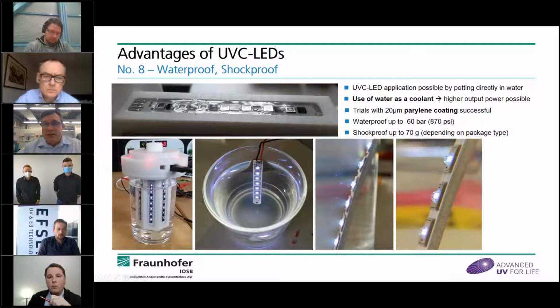But our latest research is to coat them with a 20 micrometer thick layer of parylene. They are electrically very highly insulating, which makes it waterproof up to 60 bar. And we also tested LEDs up to 70 G for shockproofness, but this depends on the package type.